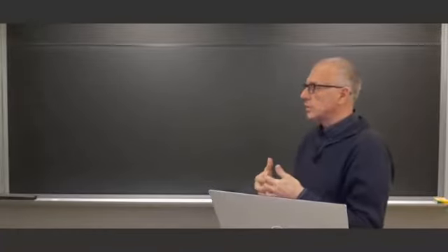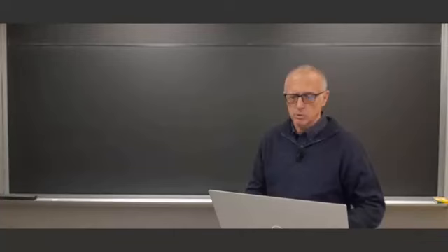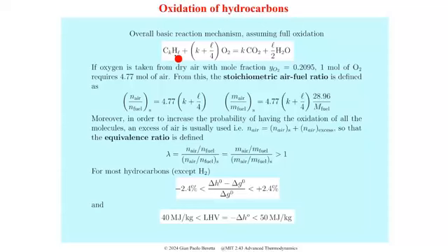So for this reason, you provide extra air, extra oxygen. You provide some excess air. So the actual fuel-air ratio that you use is more than the stoichiometric amount. And the ratio of what you actually put over the stoichiometric is called equivalence ratio.